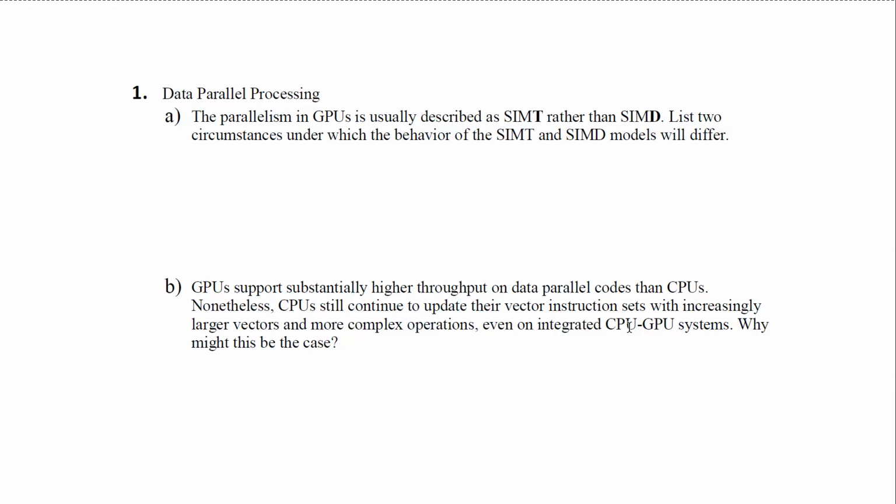What does it mean to take 32 branches at once if I'm only doing one instruction? I can compute 32 condition variables at once, build a mask out of that, then use that mask to control what happens in the next set of operations, but I basically have to build predication in software. So in SIMD, it predicates, because it has to do everything.